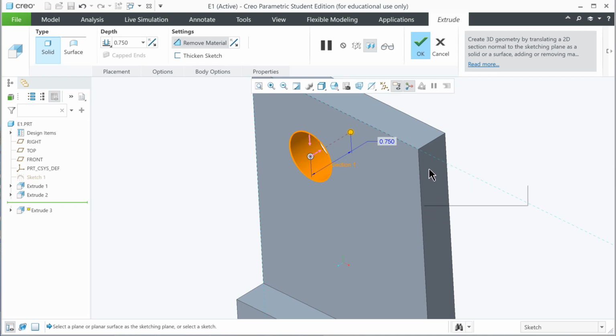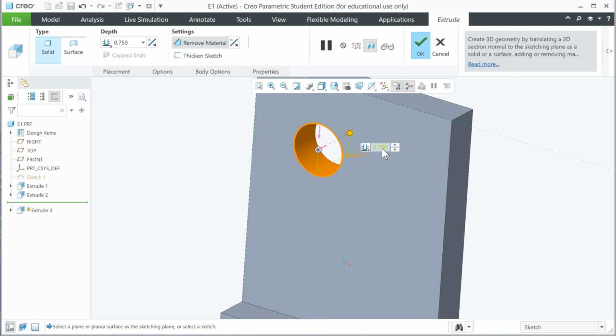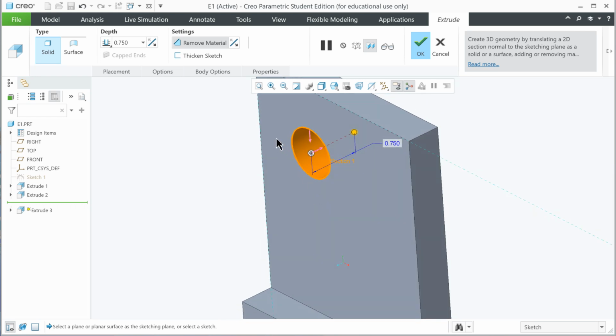And let's say this is a half inch plate right here to here. But later on, somebody changes it, like, hey, we need to reinforce it. Let's make it 3/4 of an inch. They change it because you could just double click on it. The dimensions appear, type in 0.75, hit enter, and they might think they're done. They might not check, though, that whoever designed this had this at 0.5 for the depth, and now it's not a through hole, and now the part's wrong. So here is a slight look at design intent.